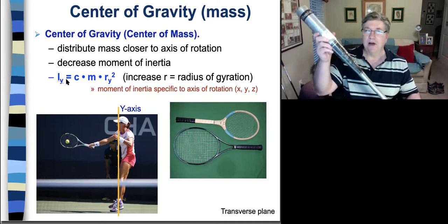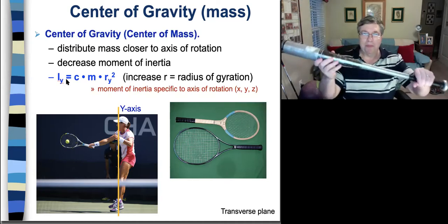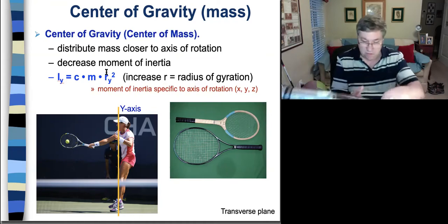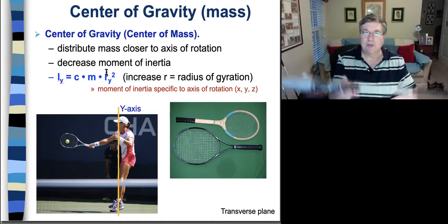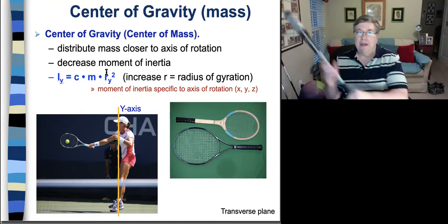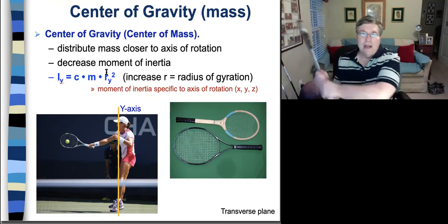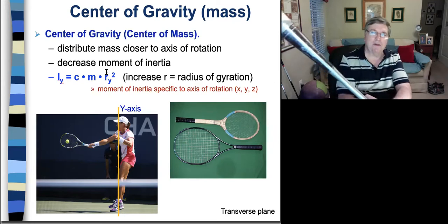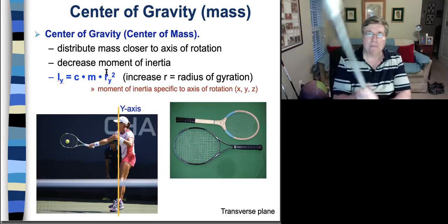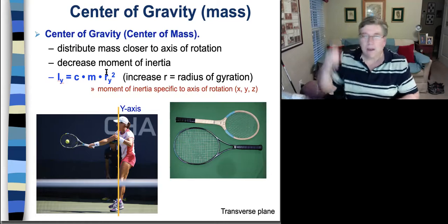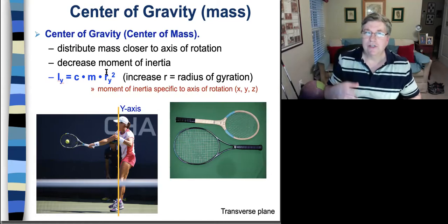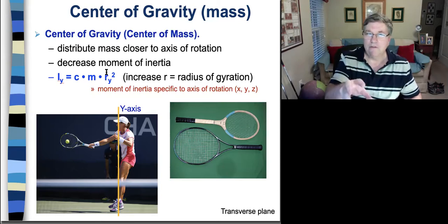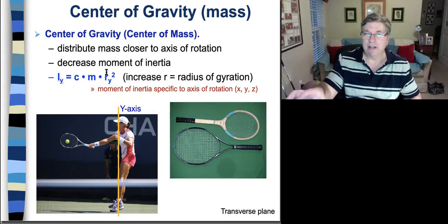The reason it doesn't help you at all is that this thing is really heavy, and the radius of gyration is pretty long. So that means the moment of inertia is high. That means I can produce a lot of torque, but the torque's trying to overcome this large moment of inertia. And we can break it down into a simple equation, believe it or not. Torque is equal to the moment of inertia times the angular acceleration.